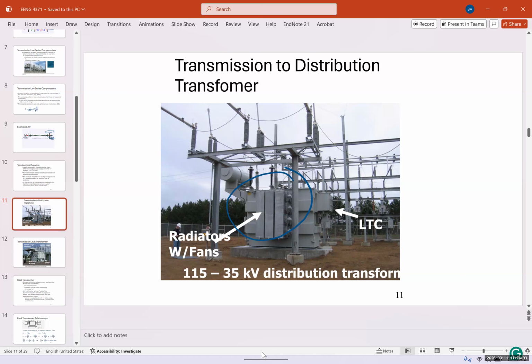It's like a car. You have to change the oil every so often, depending on what oil and what type of transformer there is. If you don't change the oil, it's going to lose its viscosity and get thickened like grease. The oil is a medium to cool down the system, and some of the transformers are dipped into the oil, and that oil actually acts like an insulator as well.